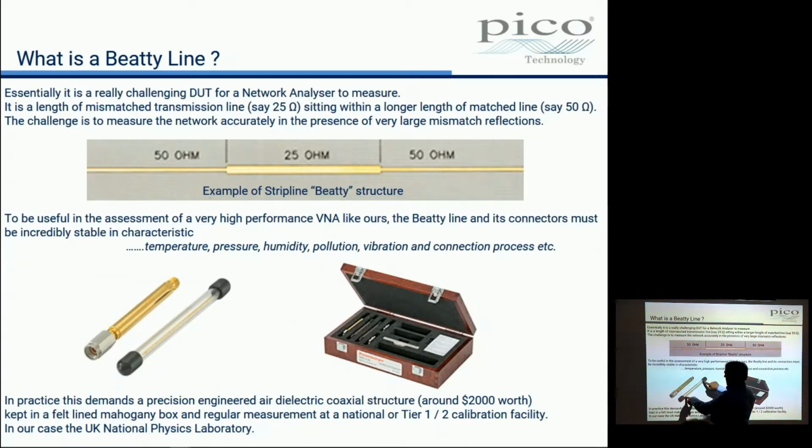So if you like, this is the outer screen. Or is that the outer screen? Oh no, the inner is in there. There's the inner in the plastic tube. Here's the outer, which has the SMA connectors on it, but no core. It's just a metal pipe with SMA or PC 3.5 connectors on it. And what we're going to do is put our centerpiece between our connectors, and we're then going to thread it through the tube and put the tube in as well.